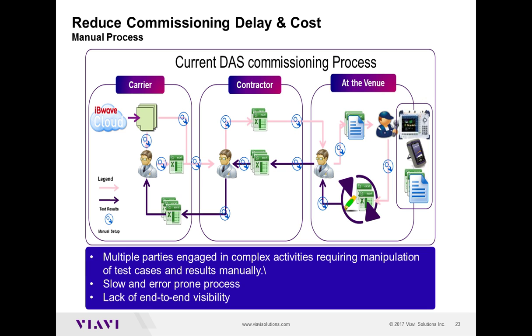Once all that work is done, then tools, don't worry about the tools that you see there, because the tools can be different. You need a cable and antenna analyzer, you need an OTDR tester, we already talked about that, the optical microscope and all those things, right? It will be needed there. So once all of those tests are done, the technician will fill out these spreadsheets, provide it back to the project manager, who will send it up the chain. As you can see, there are too many handoff points, too much manual stuff going on. So the probability of error is very significant.